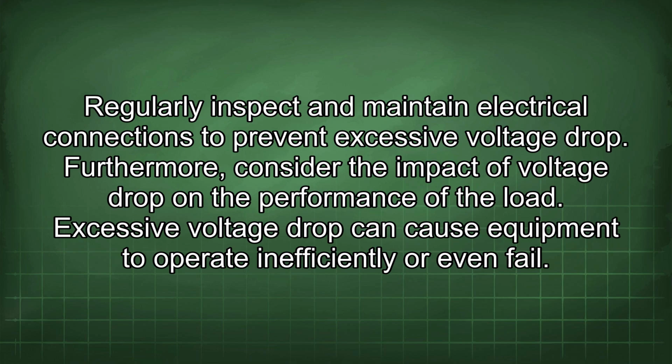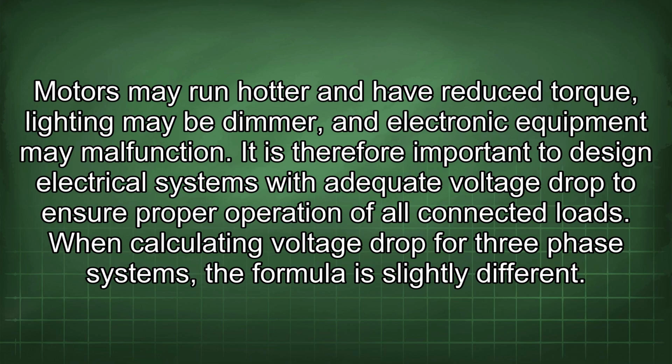Furthermore, consider the impact of voltage drop on the performance of the load. Excessive voltage drop can cause equipment to operate inefficiently or even fail. Motors may run hotter and have reduced torque. Lighting may be dimmer, and electronic equipment may malfunction. It is therefore important to design electrical systems with adequate voltage drop to ensure proper operation of all connected loads.